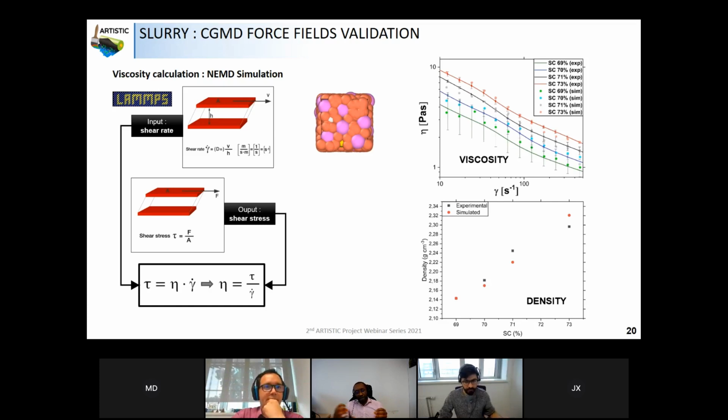For the damping factor, we don't know exactly, because we don't have any experiment that gives this value. So you will start with one value, and then what we will do is gradually change the parameter manually, or use some kind of automated tool to change the value that will give you a nice fitting of your viscosity, or of your porosity, and so on. So we make some kind of optimization of the parameters in order to reproduce the experimental result.